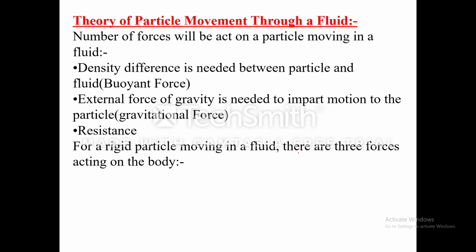Theory of particle movement through a fluid. A number of forces act on a particle moving in a fluid. A density difference is needed between the particle and the fluid, and that gives the buoyancy force, Fb. An external force of gravity is needed to impart motion to the particle, the gravitational force, Fg.